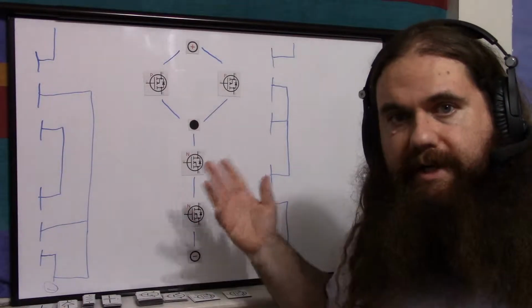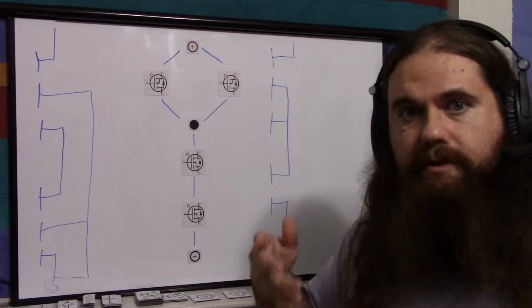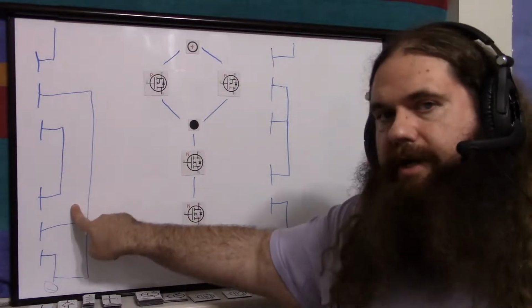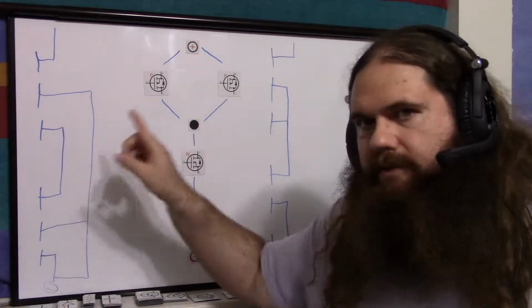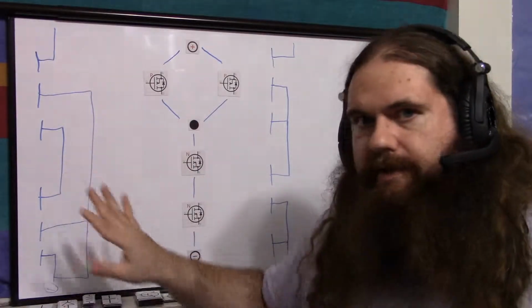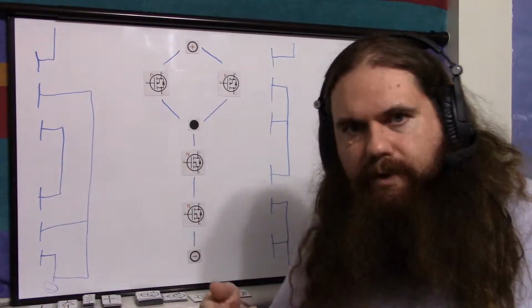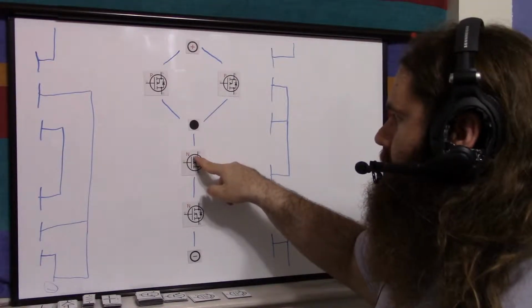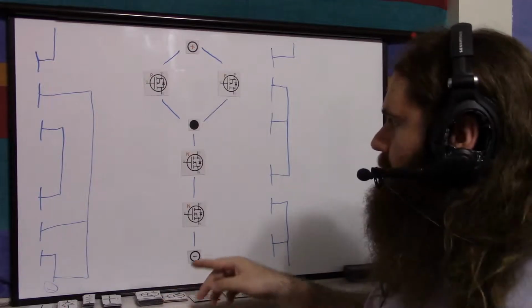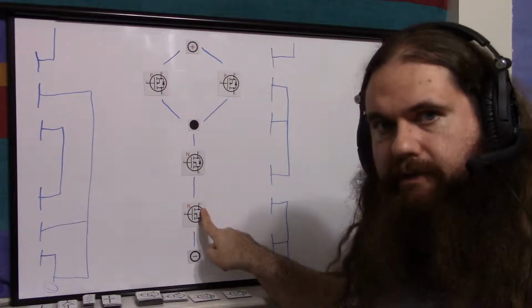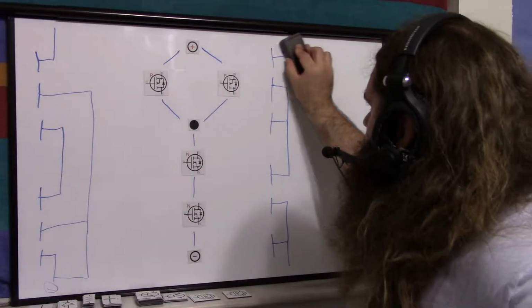I did it in a breadboard. I made a NAND gate with 2 Ps and 2 Ns. Worked fine. So just try to not get confused by this. Just look at this. Don't look at all the little wires. Try to just say, okay, they're in series, and hook them up the same way you'd hook up BJTs. You have 3 pins. You have a drain pin, a gate pin, a source pin. So in series, you take a source pin, connect it to the next drain pin. That's it. Don't worry about the wiring too much.